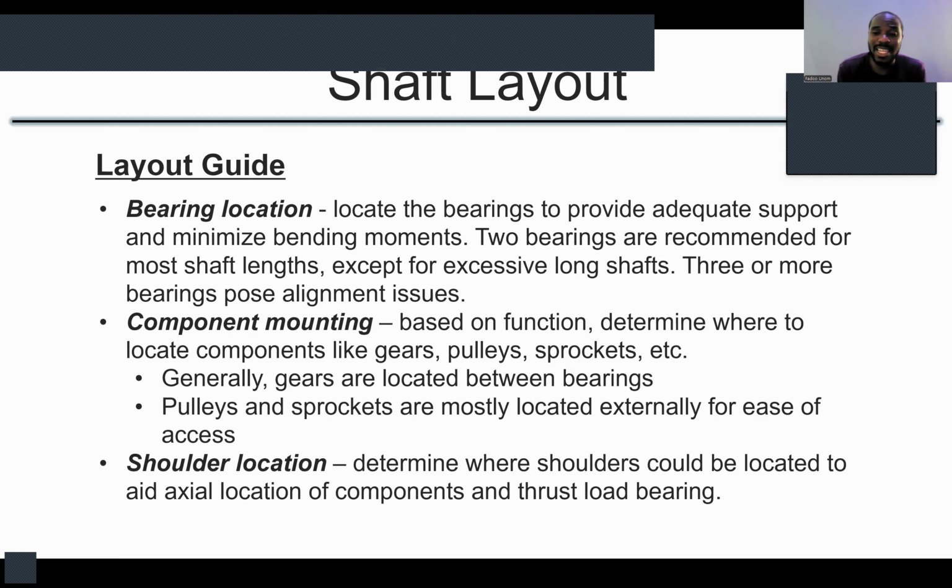For something like a gearbox, depending on the size of the gear, depending on the space available to you, you will locate your gears along the length of the shaft, depending on where you want, of course, within the limits of the available space. So it's basically based on function. So where you locate your gear, where you locate your pulley is based on function.